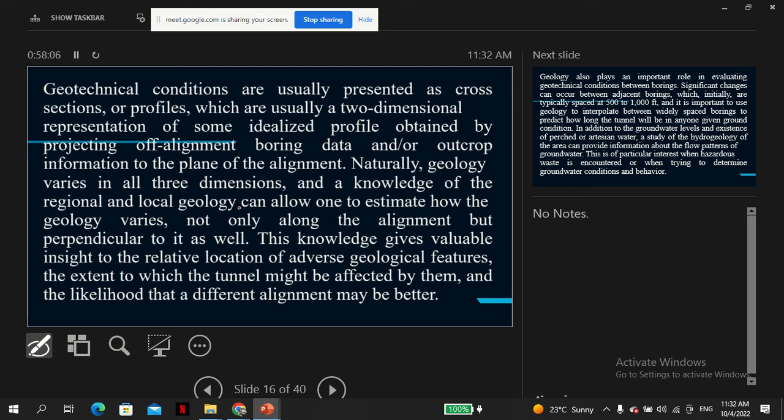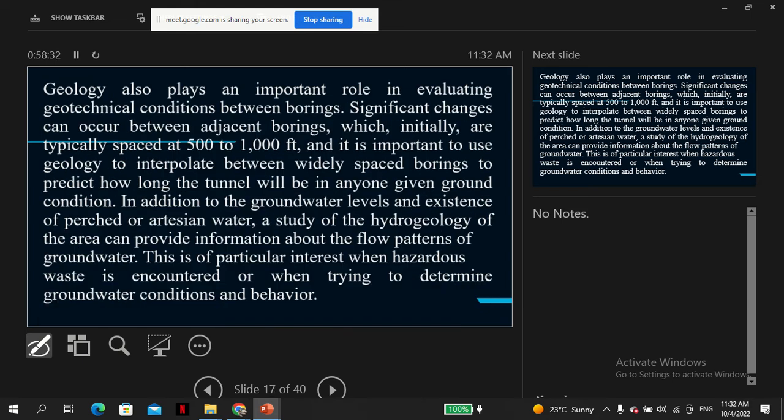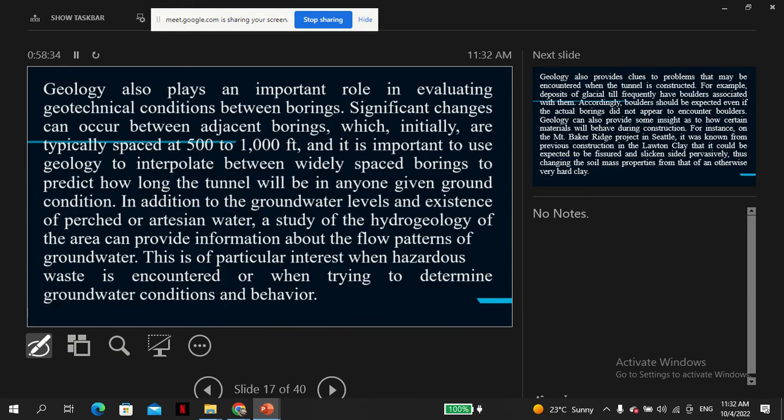So this is exactly what I was saying: if from the investigation you realize that the point through which the initial alignment were to pass has some challenges, then armed with this knowledge, you might find a less hazardous area or a different alignment that is safe.